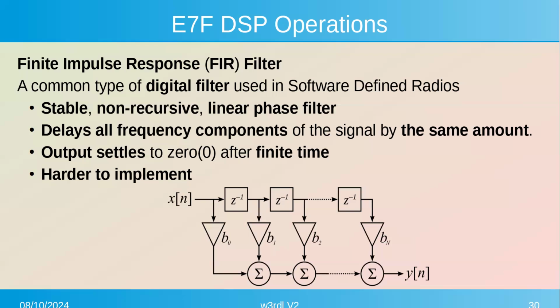Right. And actually, you can simulate one of these with a spreadsheet. And it's fairly easy. You got to do a lot of numbers, but you can generate a sequence fairly easily, and you can easily do a low pass or high pass filter. And that's all they're doing, the same kind of thing. Now, like I said, one of the advantages is it's a constant delay, because it doesn't matter what the frequency is, you're gonna shift X number of samples through that filter.